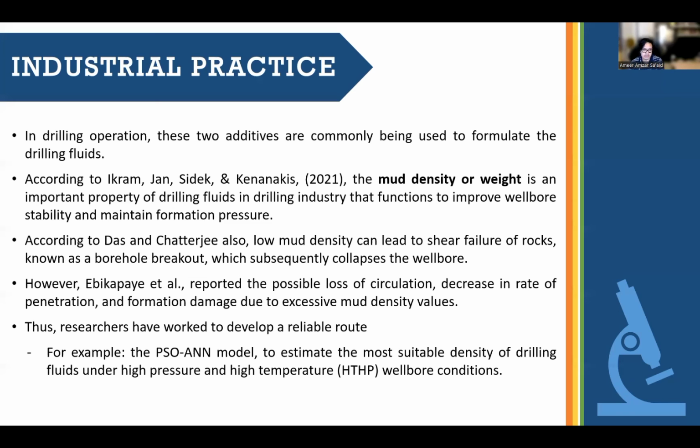Another method is adding inert, high density particulates to wellbore fluids to form a suspension of increased density. These inert high density particulates are often referred to as weighting agents and typically include powdered minerals of barite, calcite, or hematite.